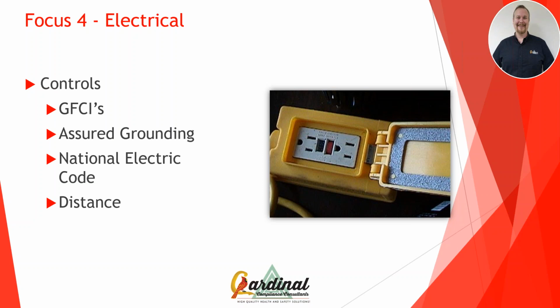Now, OSHA says you have to have one of two things in construction. If you're working outside, you have to have a GFCI or assured grounding. Now, what assured grounding is, this is where we inspect our tools. We inspect our cords, our leads, to make sure that there's no damage. Now, the purpose of assured grounding is this: reduce the chance that we could get that shock.